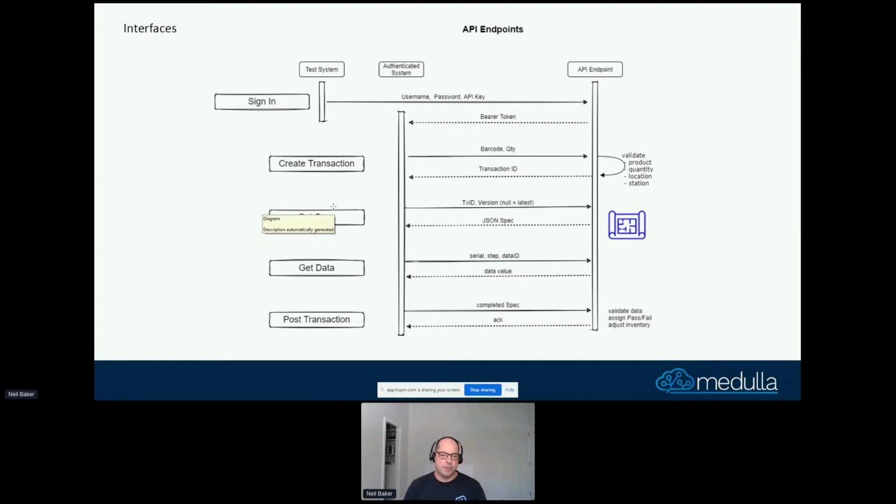And it means that if you have multiple versions of product coming through the production line, this will dynamically send down to your test station a dynamic profile with all the acceptance criteria specific to that variant. And that means that when you have products that come through, either return devices that need to go through for testing long after that version has been made obsolete, you still have a record of that and the ability to manage that and make sure that it's following the prescribed process from years back.